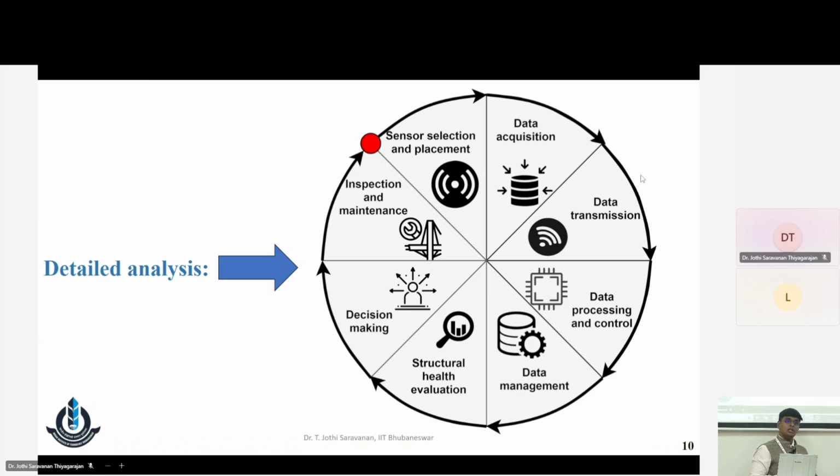If I want to get mode 2, will I get it? You cannot get mode 2 when you place a sensor at L/2. So you should have some other placement location. Of course, if you have 2 sensors, that is a different story. If you have only 1 sensor at L/2, you can get the odd modes: first, third, fifth.